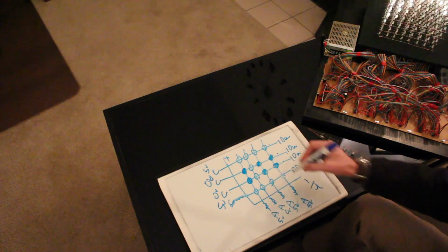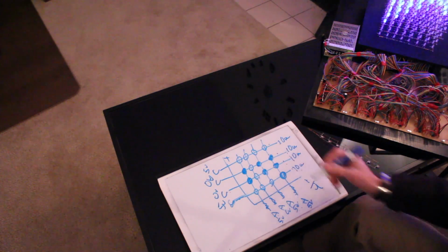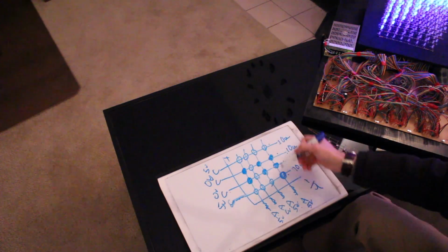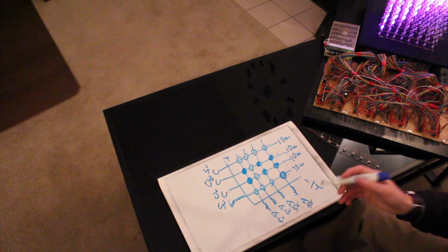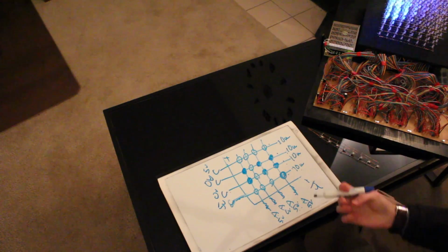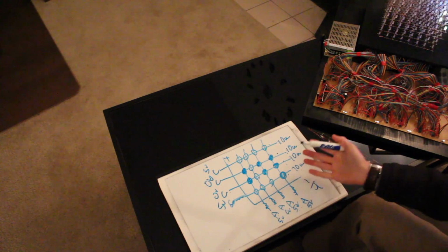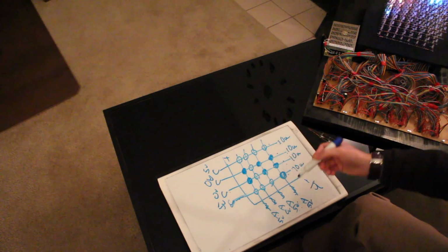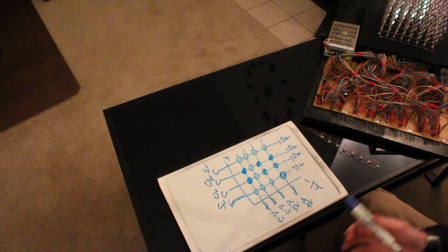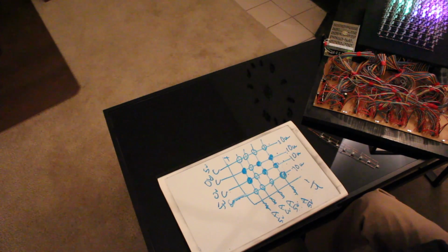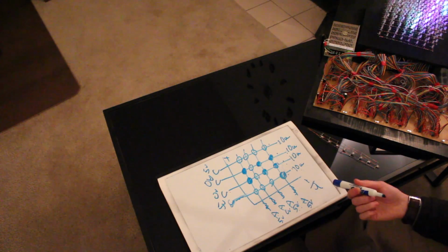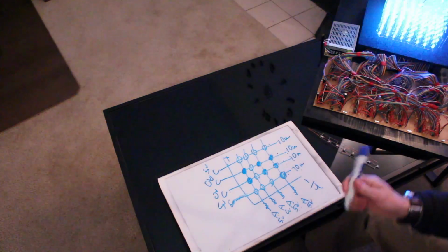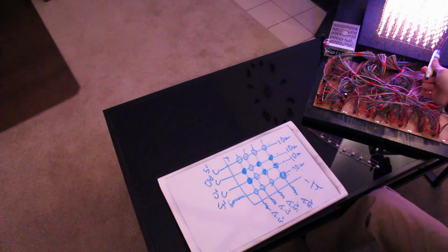So if we wanted to light up this LED at a 50% duty cycle, which means right now it's always on, it's always checking it, and it's always turning it on for its 10 microseconds. Well, to control the brightness of it, what we could do is light it up only half of the time. So light it up the first time, then turn it off, and then light it up, and then turn it off. So its duty cycle, or its brightness, is actually half of the 25% you were already at. So that's how you could control the brightness. And that's exactly how we control the RGB LED cube.